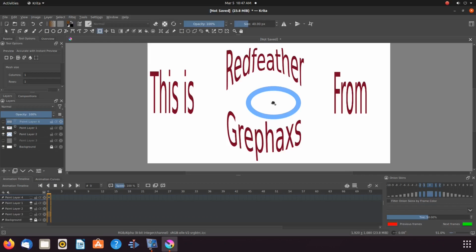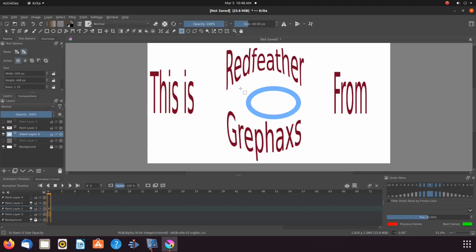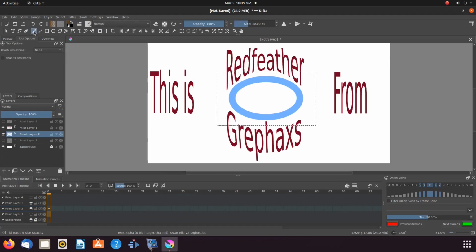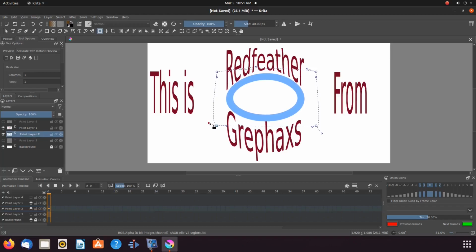But first be assured the proper Krita layer is highlighted, then click on the rectangular selection tool and then on the transform a layer or selection tool, and then Tools and Options, and then Mesh. Once this is done in Krita, adjust as necessary. Once you are done making adjustments, go to Select on the menu bar and click Deselect so as to get the final view.